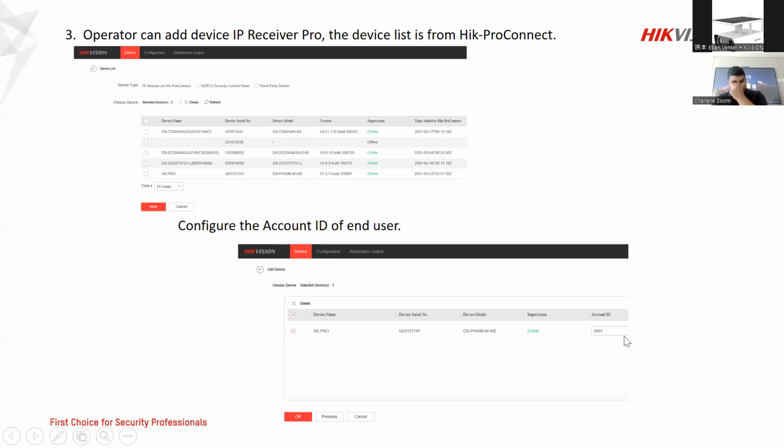What I find a lot is that customers are using the device serial number. They're using this code here, and they may be using the last few digits of it because some control room software can accommodate 4 numbers, 5 or 6. So they take the last 4, 1741, and put it in here, and on the other side they've got an account number that they're following, and they say, okay, they're going to use 9001. There will be a problem there because it's looking at 2 different account codes.